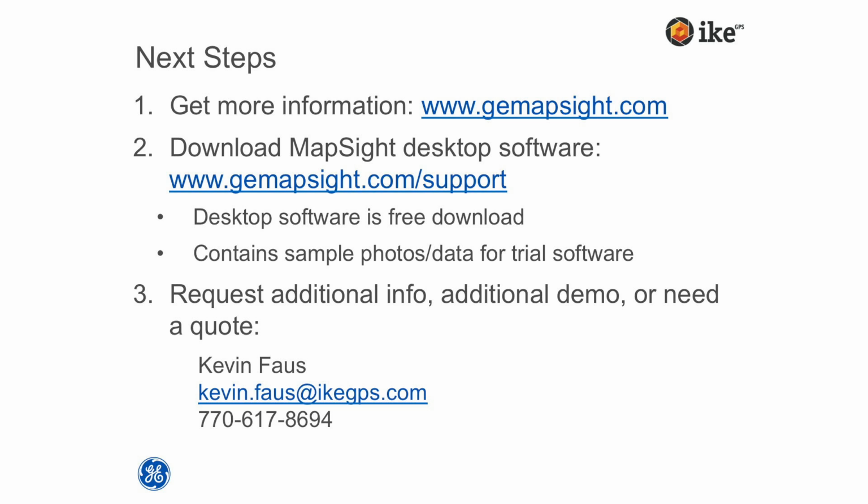Are the lat and long coordinates in the CSV for the pole target or for the position of the MapSight unit at the time the data was collected? The lat and long coordinates in the CSV for the pole target are for the pole target. Now, you do have the ability in the custom form workflow development, if you want to export the coordinates of the unit itself, you have that ability.